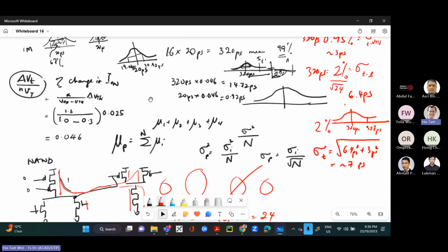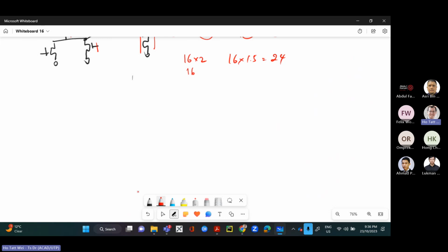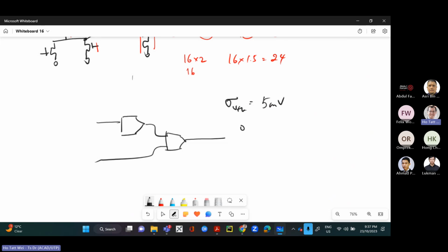So walking through all of these like that, but you know, in the exam, I can give you something like this, right? I can actually say, okay, this is the circuit for maybe a full adder, right? Or a comparator, right? So I can have maybe my majority gate here for full adder kind of thing like that, right? Then I would say, for example, if you have a process variation, I can say maybe VTH is, maybe I give you certain 5 millivolts or something like that. And then the variation in channel length is maybe 5% or something like that. And then I'll ask you to estimate what is the timing variation, or I can give you a circuit and I just give you values and then ask you what is the impact on the circuit.